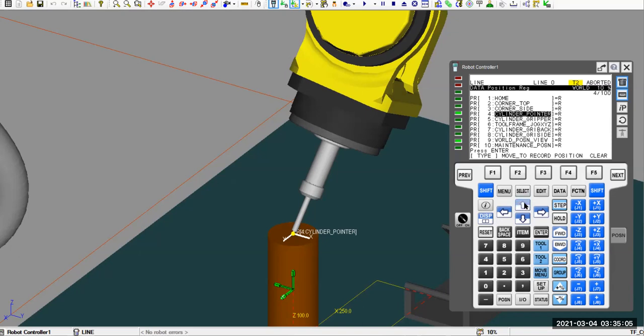Now I'm going to switch to a different tool. With the simulation, we can use what we call the jog menu. Shift and coord, you're going to bring this up. Once you bring this up, right now the tool is on number 1. So a Fanuc robot has 10 different frames, so we can match each frame to a different, separate tooling. Over here, if you press dot, that will be the last one, number 10. So I'm going to press dot on my keyboard.